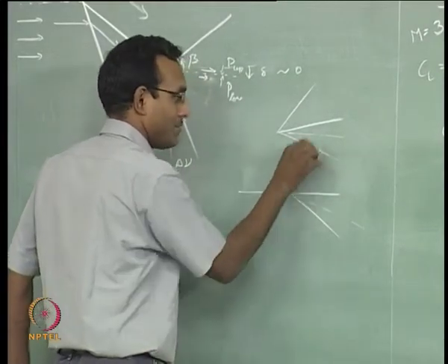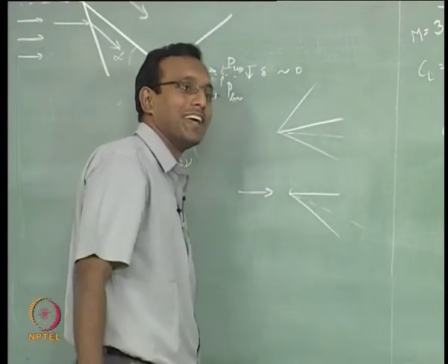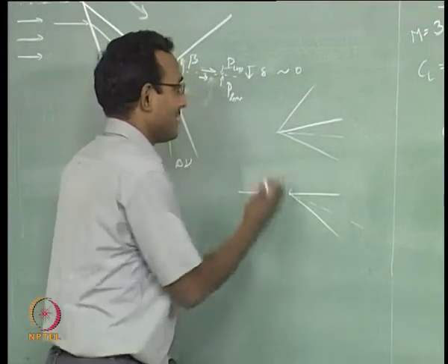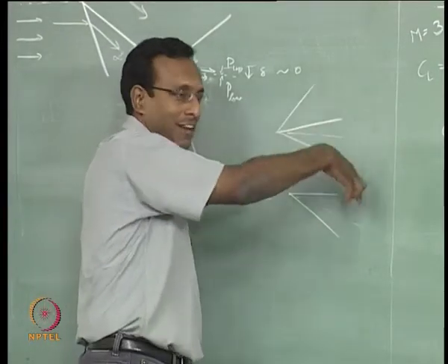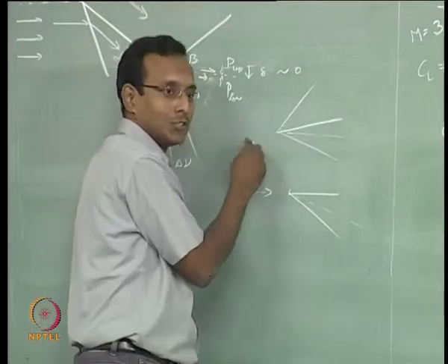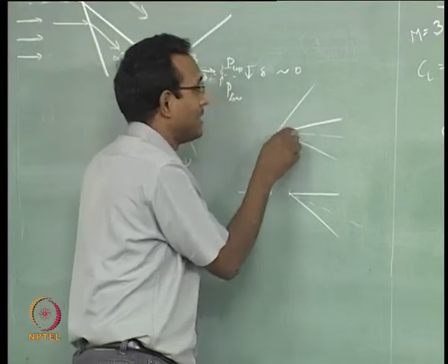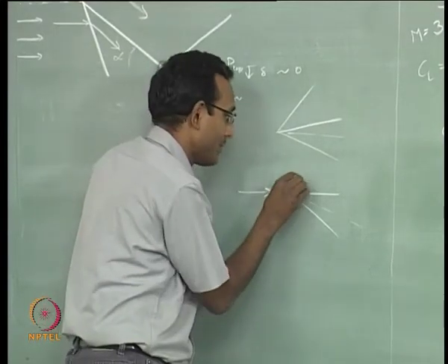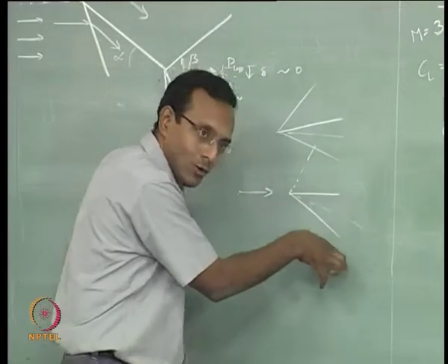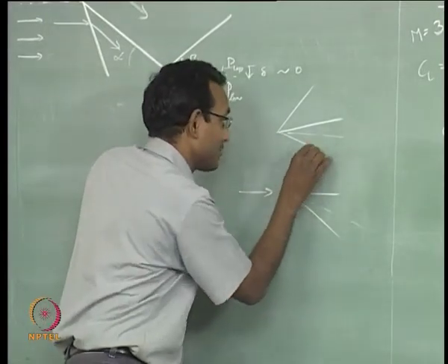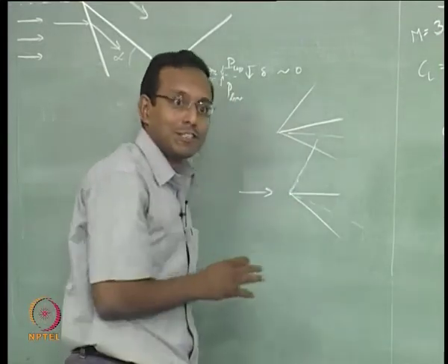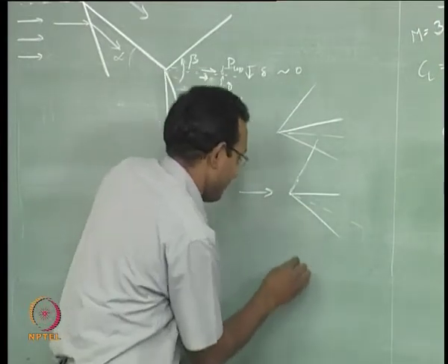What wave will be there on the top? No wave, I do not like that. There is always a wave and we call it the Mach wave. If I think about the continuous change of angle of attack, what is really happening is this oblique shock is going to become weaker and weaker and weaker. Eventually beta will become equal to mu. That is where it has the weakest oblique shock, the Mach wave. If I go any lower, that Mach wave does not change, it stays there, but there are more Mach waves downstream which eventually form your expansion fan.